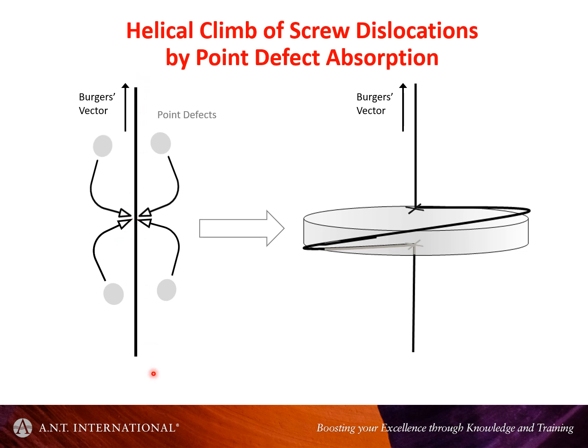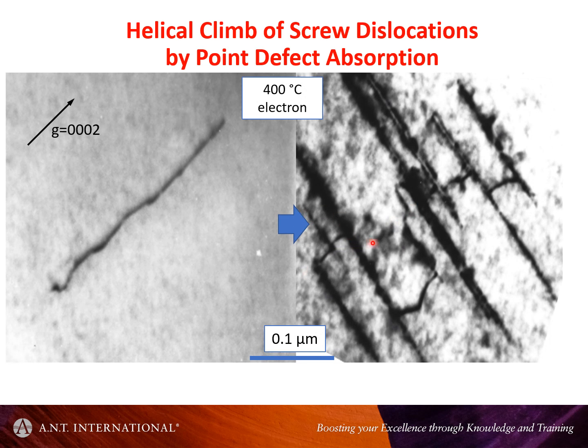so that when you irradiate a sample with screw dislocations, in this case a c component or c plus a screw dislocation, you get this nucleation or accumulation of point defects, which gives rise to what's called helical climb. And this is just the same as the loop formation, except the nucleation stage is made easier by having the dislocation. So in irradiation, this is an electron irradiation example, something I did in the Max Planck Institute way back in the 90s. I took a c plus a dislocation.